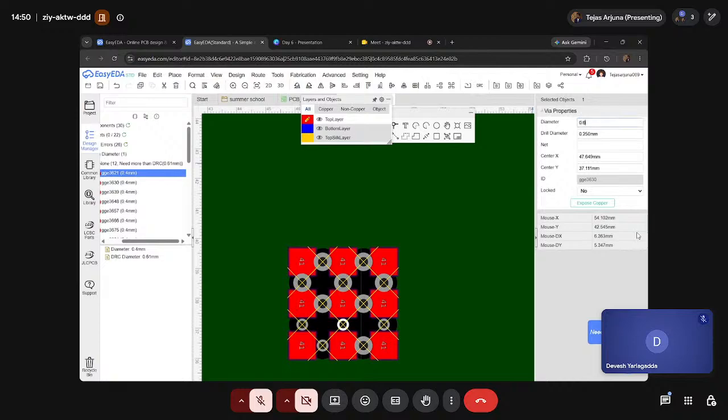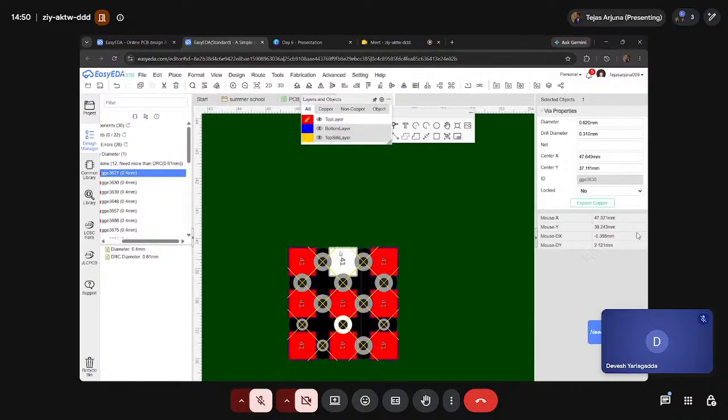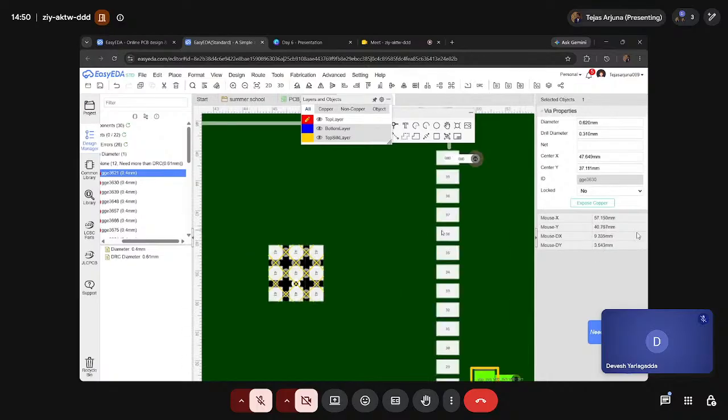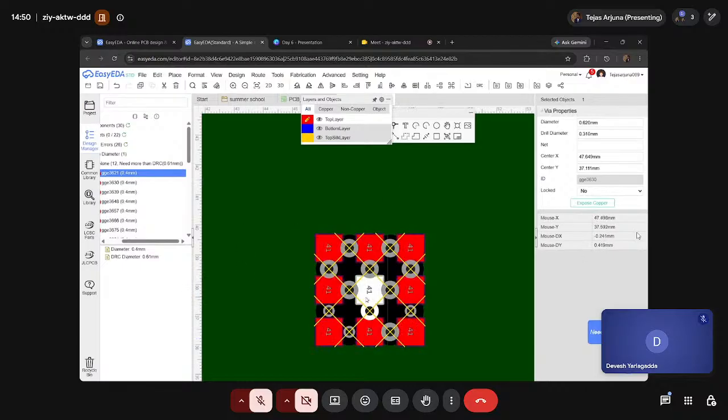Not only in these thermal wires, but in any wires and pads that have the same net, we can overlap them. We can also place this wire directly above it. But since it is part of the footprint of the ESP32, I cannot change the wire placement. I cannot shift it over here. They must be kept in the same place.